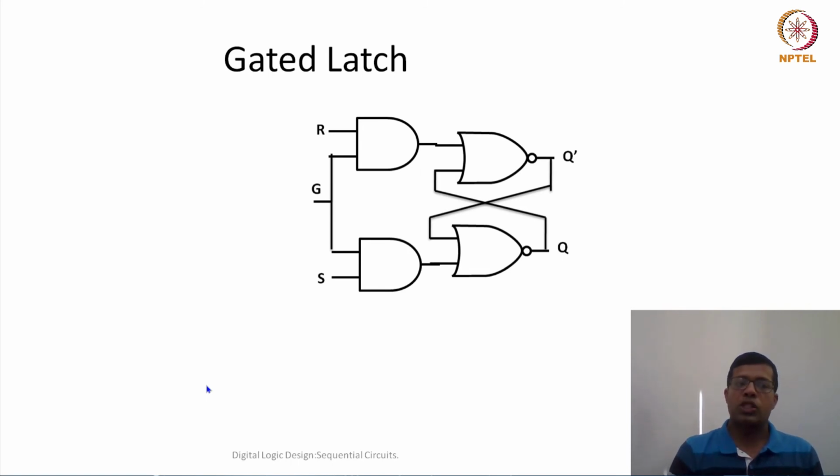Now we were talking about the clock signal sometime in the initial part of this lecture. So this clock signal is a common control signal which is found in most of the synchronous designs. It will make sure that changes happen only with that control signal. That control signal will define when to store into my latch, when I can avoid storing, or when this input would be given to the output, or when it would be gated.